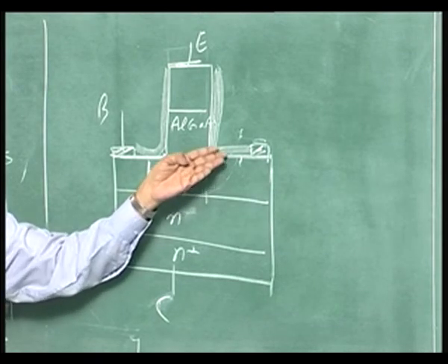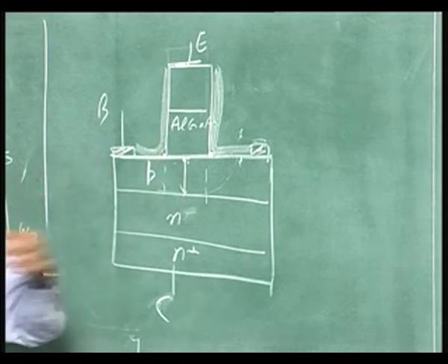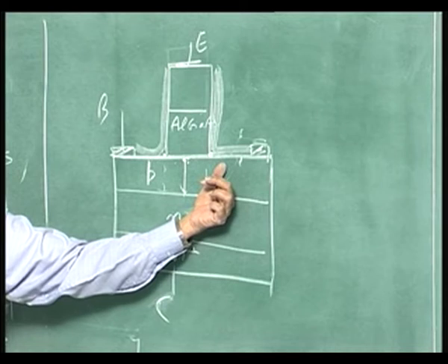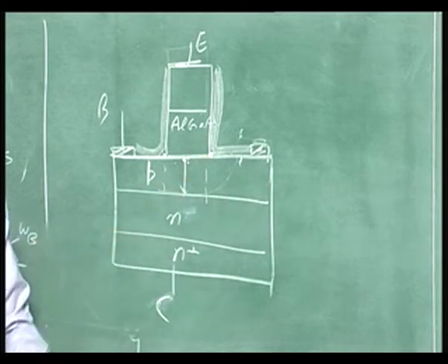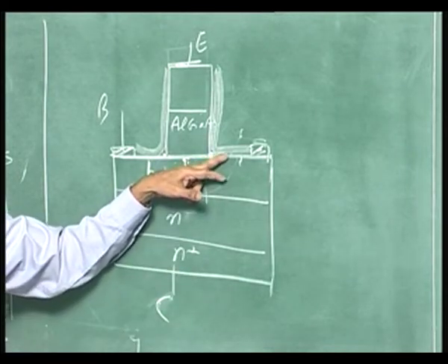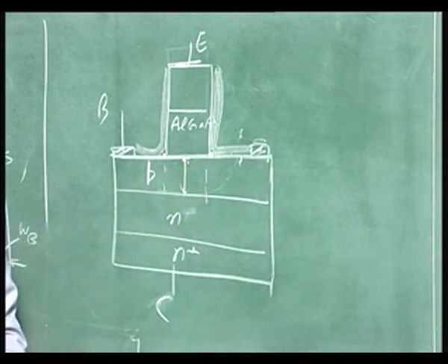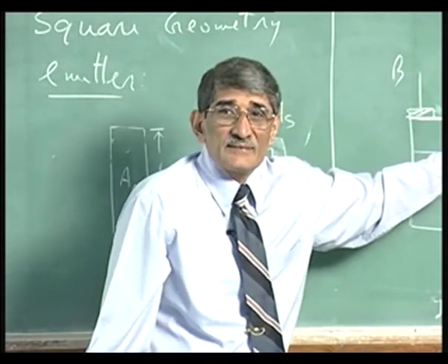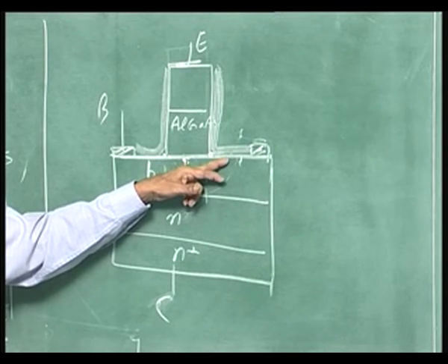because that SiO2, any oxygen containing layer, will react with gallium arsenide to release arsenic from the gallium arsenide. But then you say put nitride, and these are the steps taken by people. Instead of oxide, put nitride. When you put nitride, what happens?